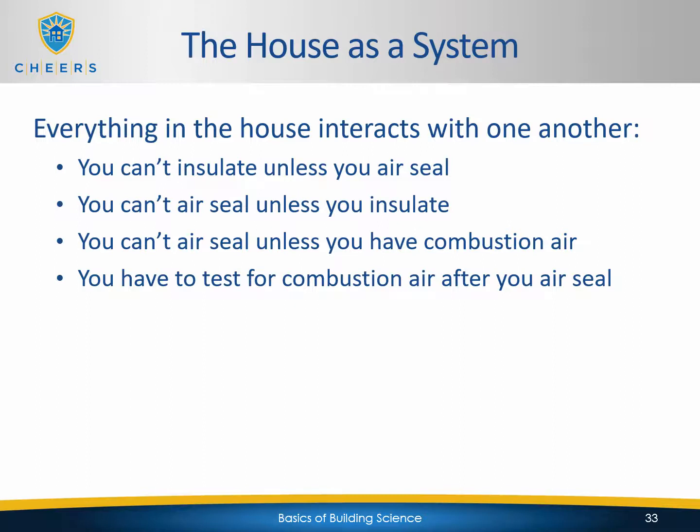And then you have to test for combustion after you air seal. Every time you air seal a house and you basically tighten it up, the pressure boundary of the house is now much tighter. There's the potential of a dangerous situation being created with your combustion appliances. So it's important that you test for combustion air after air sealing. Basically you have to make sure that there's enough makeup air for those combustion appliances to work properly.